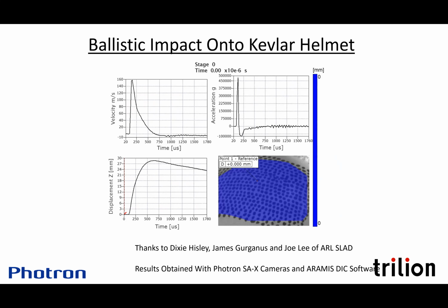And I was able to just stop what I was doing and on the fly say, look, if we're not finding one camera in the stereo pair, the quick, easy, known solution: do a hard reset on the camera. Then it has a known IP address, hook it to a known Ethernet port, get back talking, and then set it up the way you need it. So yeah, training and support go hand in hand. The more training we give, the less support we would have to give. So we're always looking to make more, I call it portable support solutions, self-contained videos that, just here's a link. This will tell you everything you need to know to answer the issue you're having right now.